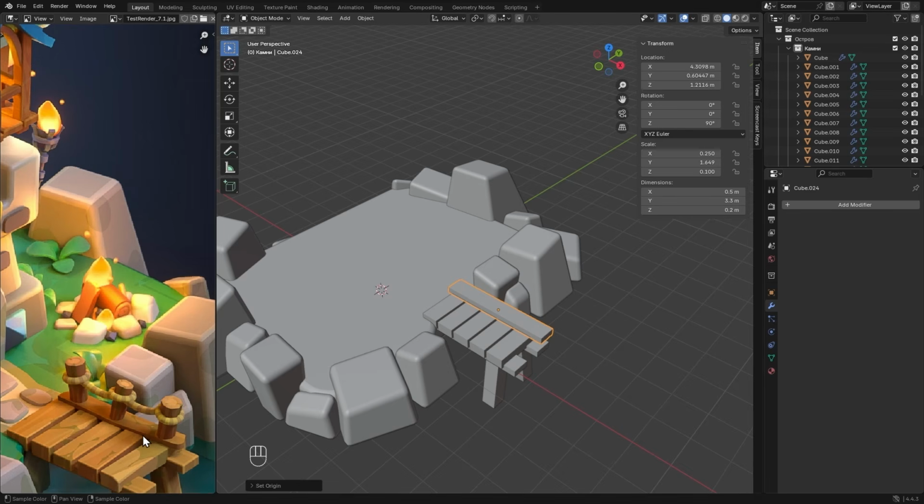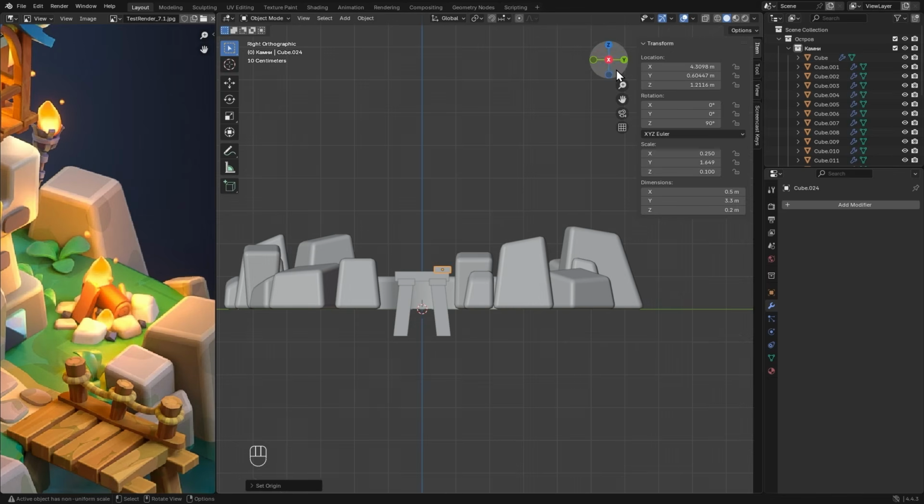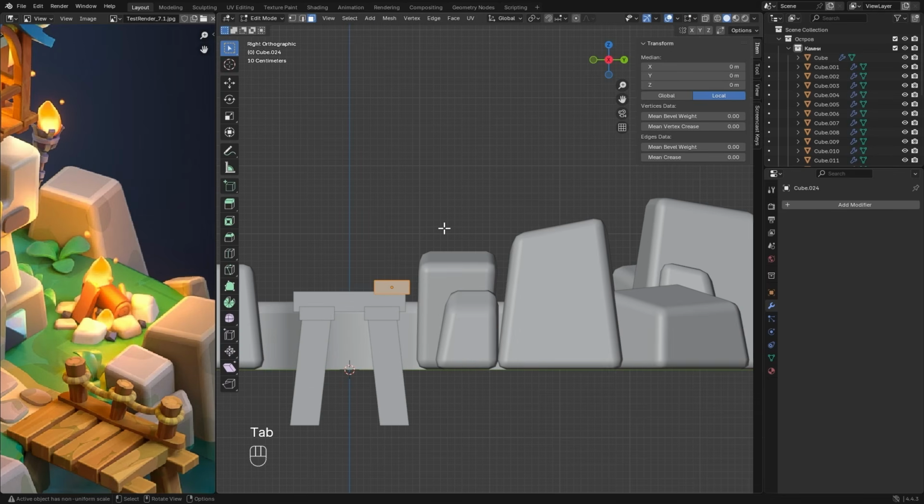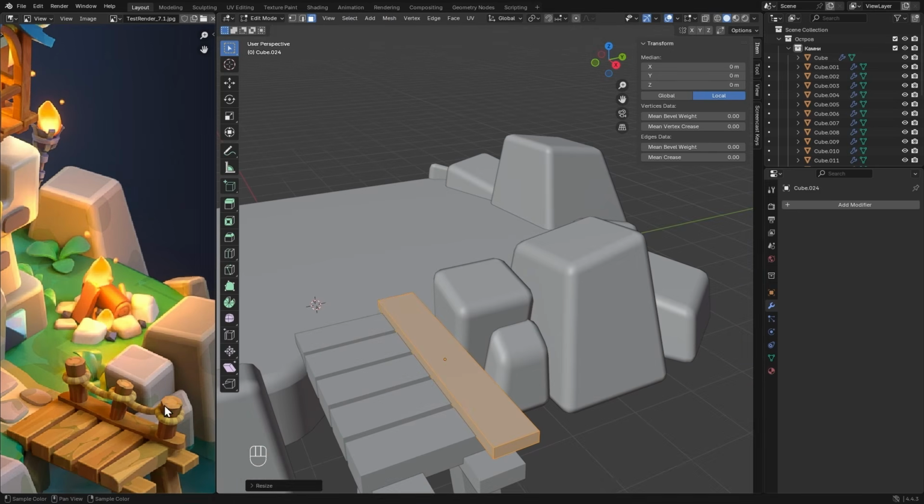You can also notice that this plank looks thinner than all the others. So let's go to the side view, into edit mode, and scale it down along the Z-axis, SZ, to about here. It also has a specific shape, some bends right here, here, and here. Let's move this edge a little bit back. For this, I double-tap G, activating the slide tool, and shift it backward.